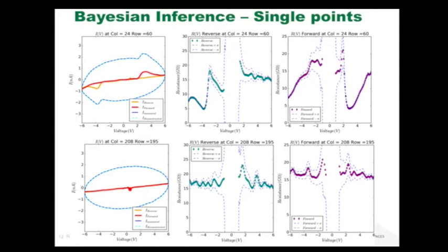and this is definitely true of polarization reversal in ferroelectric capacitors, then very often you will miss those in the standard IV measurement, but you can capture them in your fast IV measurement because this is a dynamic mode of acquisition. So that's why we call it the general mode of IV acquisition. It really is dynamic. It's not a static, quasi-static measurement.